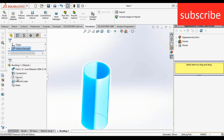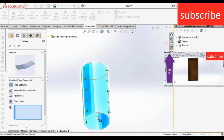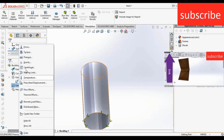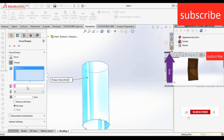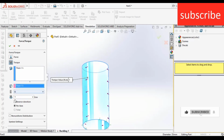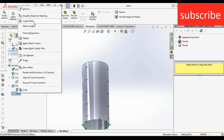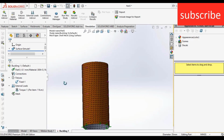Now right click on fixture, click on fixed geometry. Select this edge, click OK. Now right click on external loads, click on force, select this face. Make sure the value is 1 Newton because a high value will create a problem. Click OK. After that, right click on mesh, create mesh, increase the fineness, click OK.